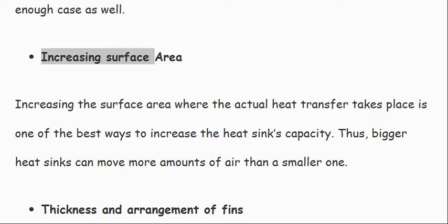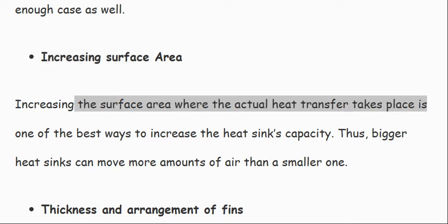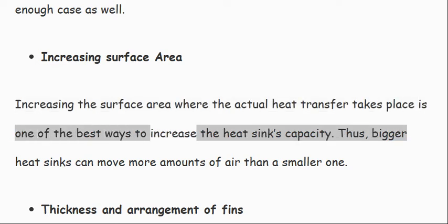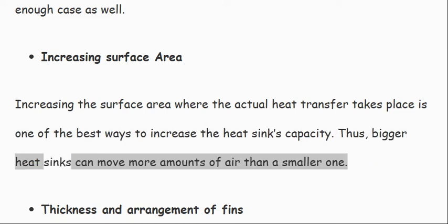Increasing surface area. Increasing the surface area where the actual heat transfer takes place is one of the best ways to increase the heat sink's capacity. Thus, bigger heat sinks can move more amounts of air than a smaller one.